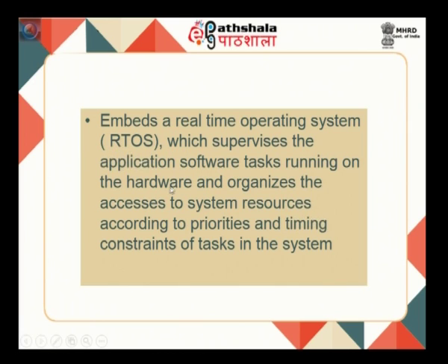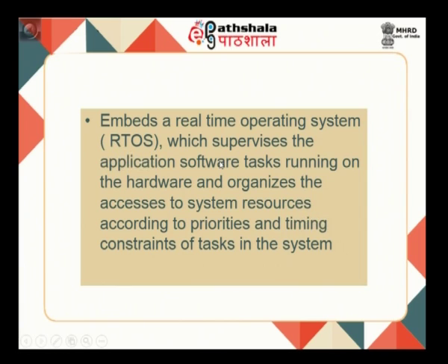It supervises the application software running on the hardware and organizes access to the system resources according to the priorities and timing constraints of tasks in the system. So, you see that this operating system monitors the hardware as well as the software and organizes access to the system resources, and based on the priorities the tasks will be assigned.